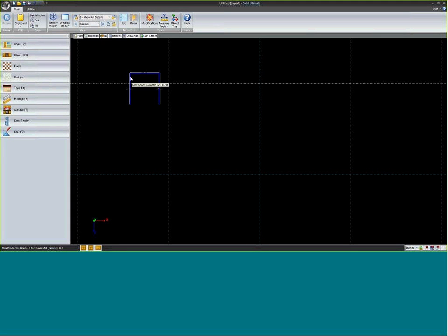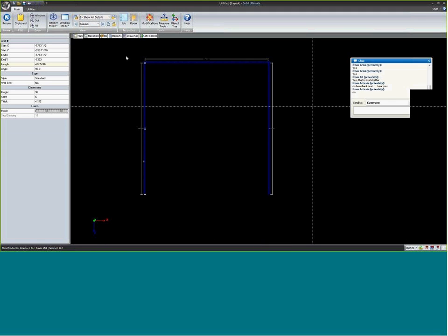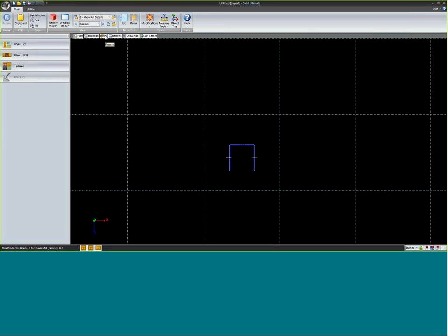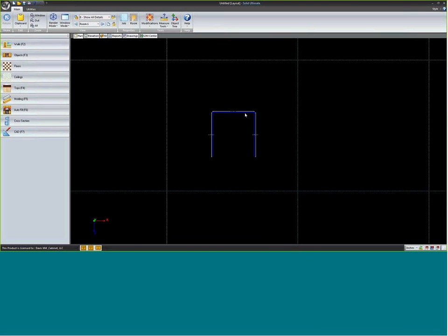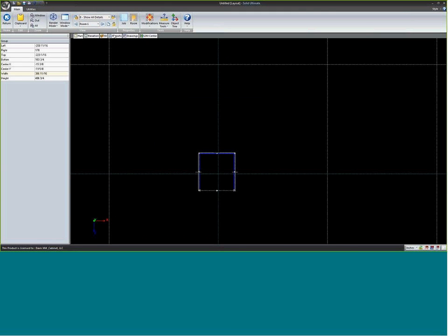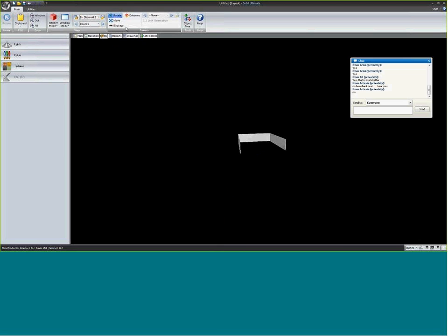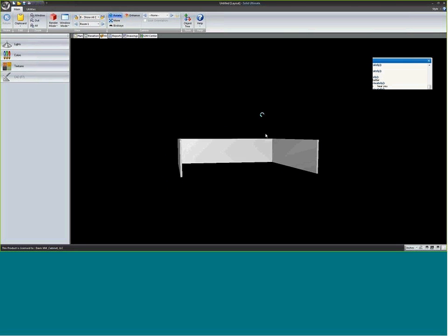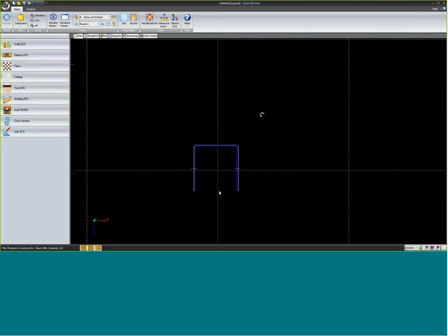If I select those walls and move them over here closer to the vision point, I should be able to zoom out. There's the bird's eye view. But notice how it moves things around me in a weird way, and there it starts to chop off part of the room. That's because of that location in the room. So I always want to take the room layout and try to build it around the center of a room. Now in 3D, I can get a lot better view, and actually be able to zoom and pan and do all the things that I need to do.